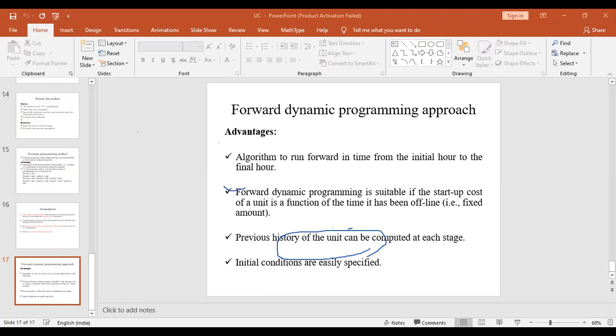Here PL represents the losses. The total losses plus PD, the demand, are assumed for calculating the total power generated across the nth number of units. This is a simple representation for calculating the power system losses, and also for calculating the economic load dispatch including the losses of these systems.